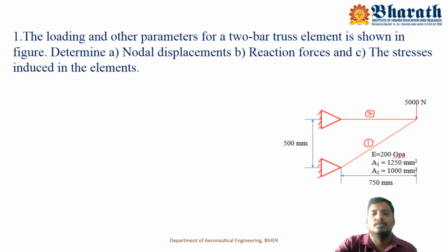Then we try to solve this problem because we already derived the finite element equations. The problem is the loading and other parameters of the 2-bar truss element shown in the figure. Determine, first, the nodal displacements; second, the reaction forces; and third, the stresses induced in the elements. So the given structure is a 2-bar truss element.